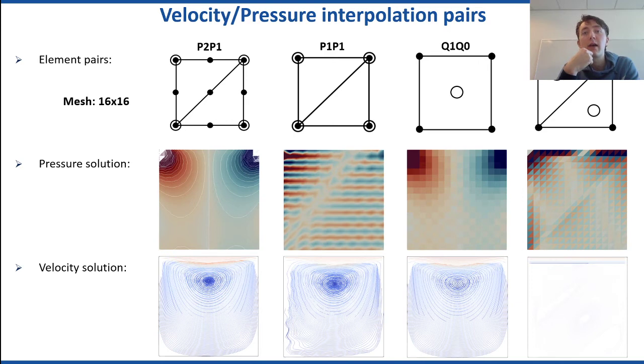And as I think I've shown this before twice already, the point here is that the spaces for the pressure and velocity are in principle independent of one another. You could choose different spaces for these two solution fields, for the velocity solution field and for the pressure solution field. But depending on our choice, and we'll get back to what these choices mean exactly, depending on the choice of function spaces for those two fields, you get wildly different results.